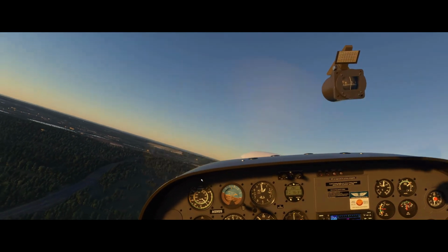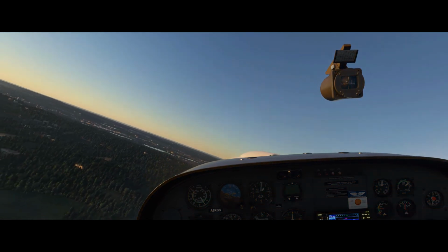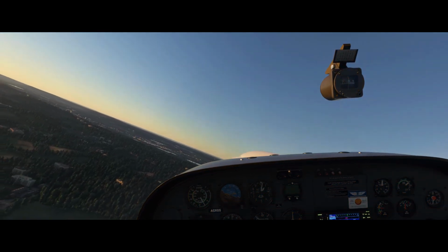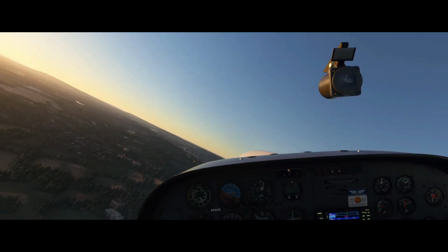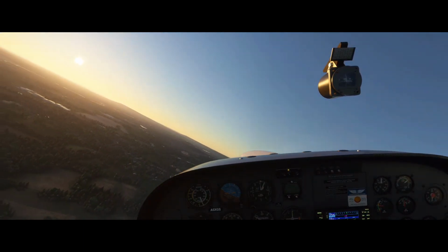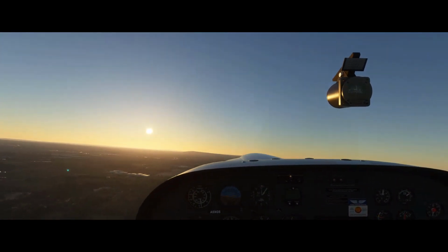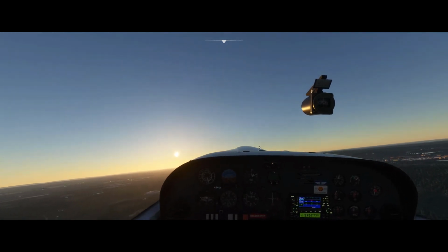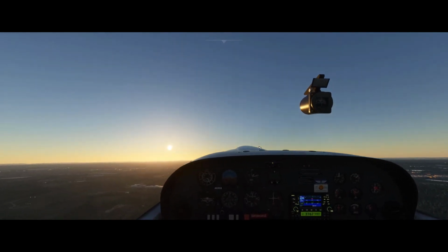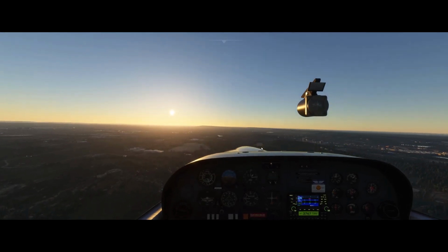This is on the downwind leg, so downwind leg being that we are going to parallel our landing runway but in the opposite direction. We know that we took off on 08 right, so our parallel should be around 260 in terms of heading. So you can see the aerodrome there. We're a little bit, yeah, there we go, 270, 260. Just gone through 1200s.